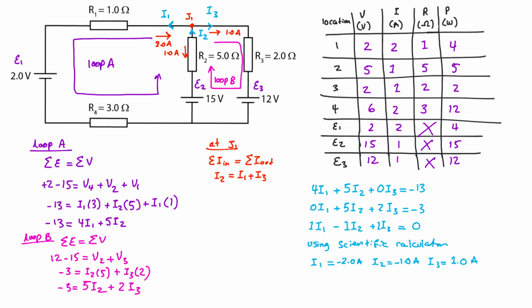And that's for the voltage law, and you can use Kirchhoff's law for current as well. Just take a junction. In this case, we only have two junctions, so you just have to choose one, because the equations for both are going to be exactly the same. You have the same currents coming into those junctions and the same ones going out. By that I mean you're dealing with only I1, I2, and I3 for both junctions, so they would give you the same equation in this case.